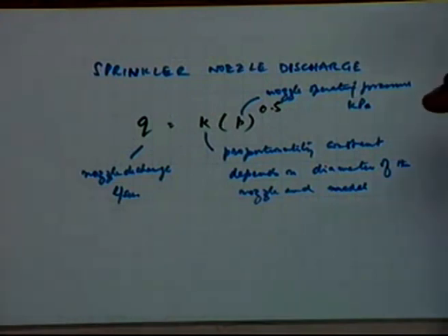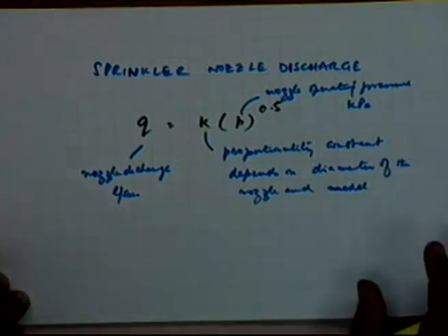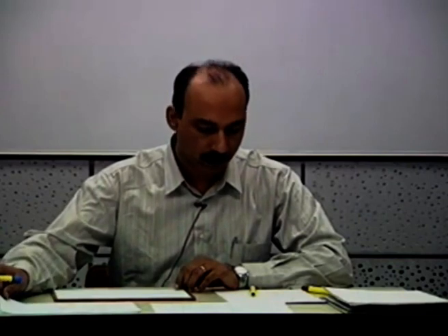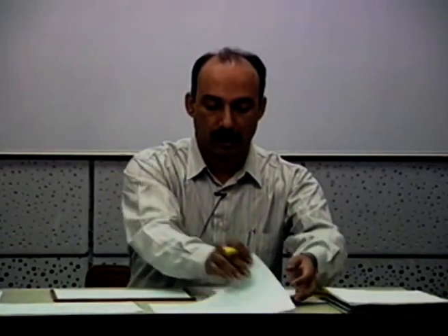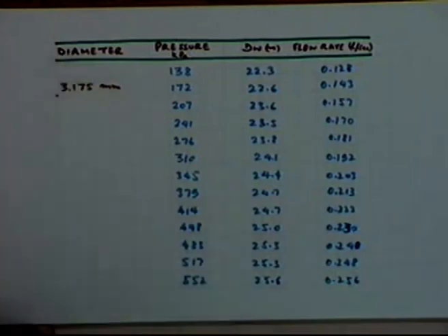When a manufacturer comes out with a new model of the nozzle, they will give you an accompanying table which will have all these different items which you are interested in from the point of view of the discharge calculations or for other design parameters. Those things are normally made available, and a typical table which will be made available for a specific nozzle.